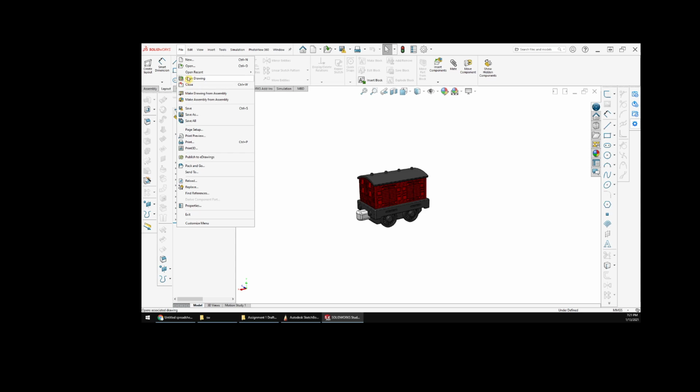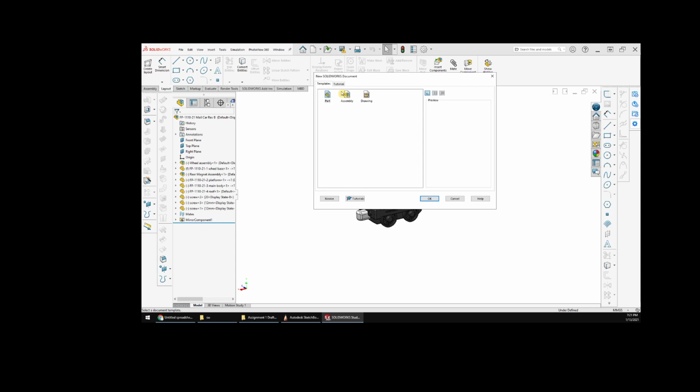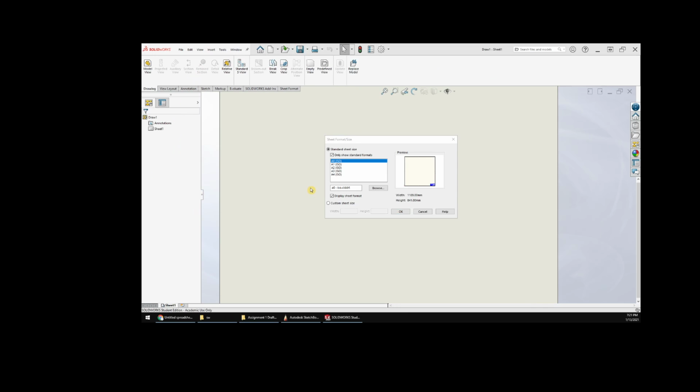So for this, we're just going to go new. We're going to make a drawing. We'll get into later on, but there's different templates that you can do. There's also some tutorials that I'll have you do as well. Get back to drawing. We're going to go OK. Now, right off the bat, you want to set up your page. What are you going to draw on? You've got A1, A2, A3, A4. This part was done in millimeters, so it's giving you the millimeter sizes.